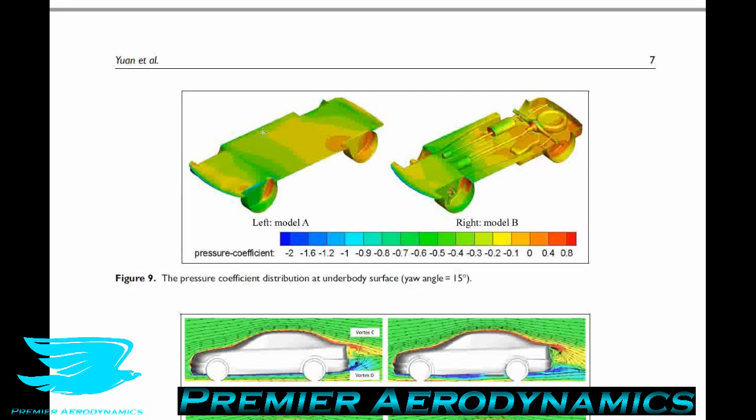What is happening here, I think, is that the flow coming over this front leading edge effectively is separating, because this is quite a sharp corner, and then it takes quite a lot of distance for it to finally reattach, and that's what's happening here. That's when we get an increase in pressure back here. So the flow is finally reattaching here.